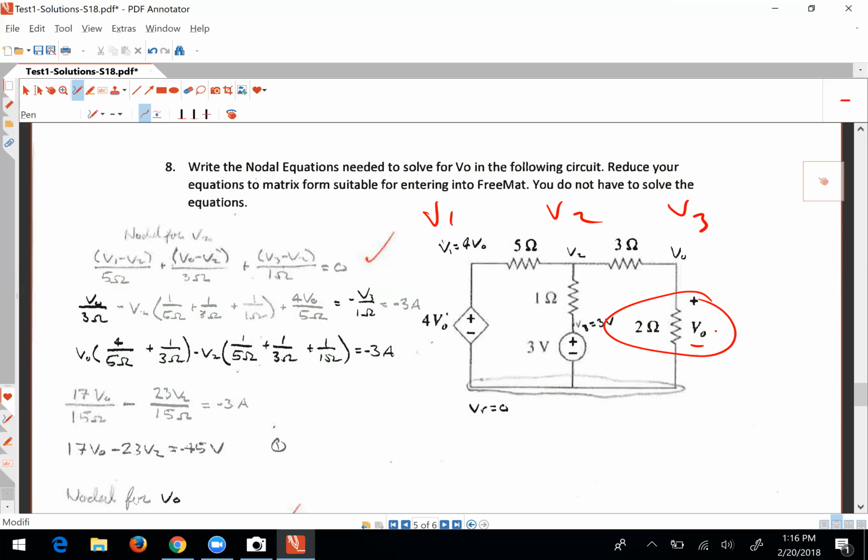This is something we run into a lot, and these guys here are not floating voltage sources. These do not call for a supernode. That's inappropriate for this kind of circuit. These are just regular voltage sources attached to ground. And so a lot of people just went and did a supernode thing, which made them really kind of messed up. Because that's not when you do a supernode.